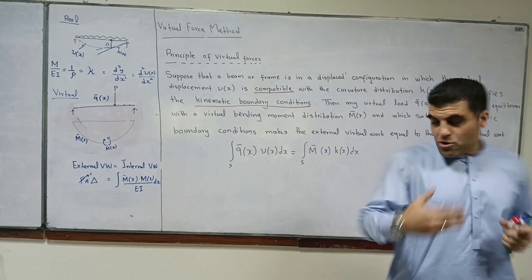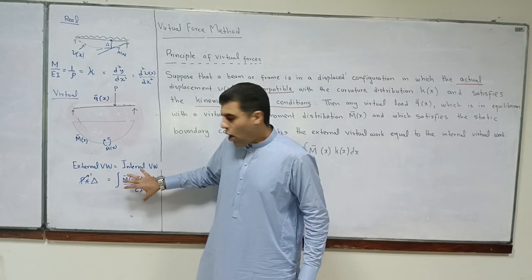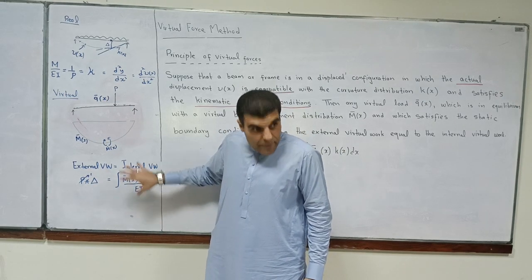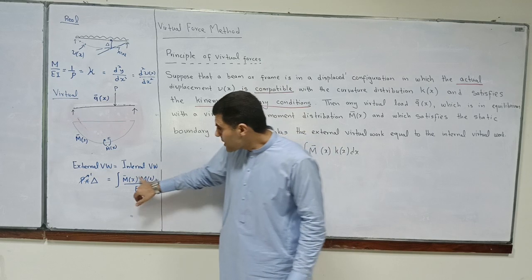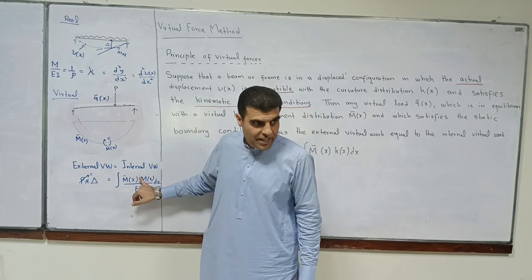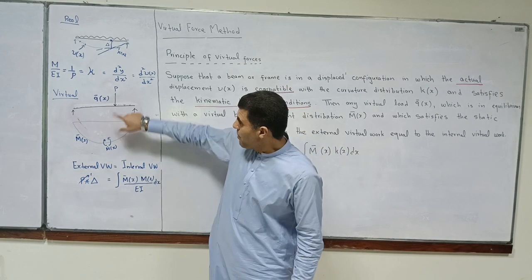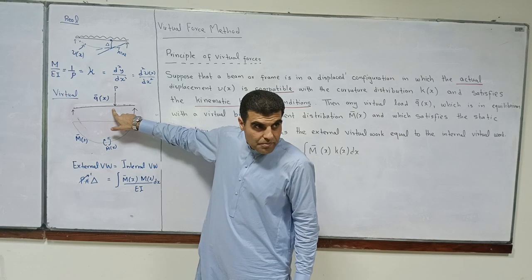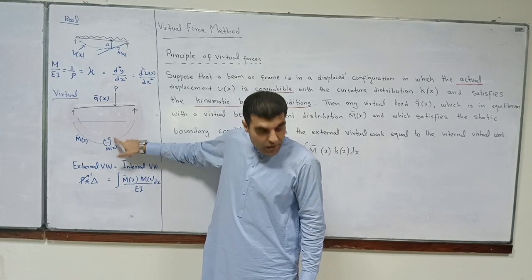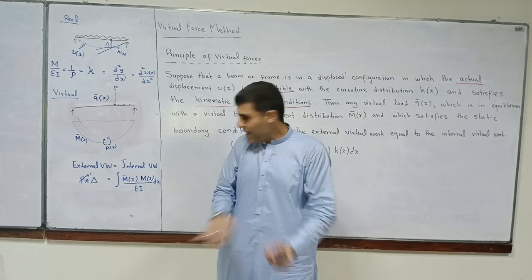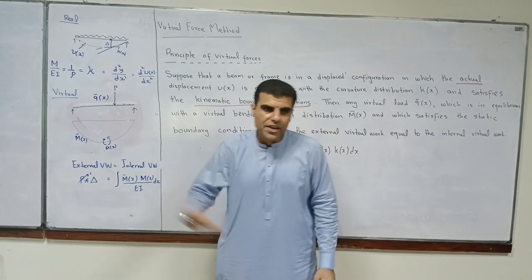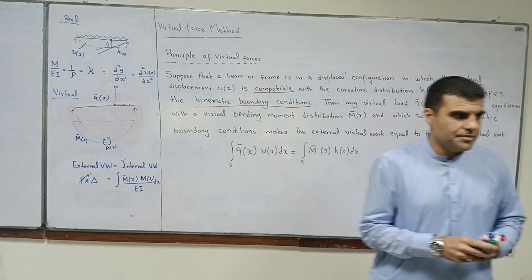When you apply it, you can apply this formula on beams and frames. But notice that you have to work out your moment equations. So there will be two moment equations, one for the virtual and one for the actual. You multiply them, you integrate them and you get your deflection.